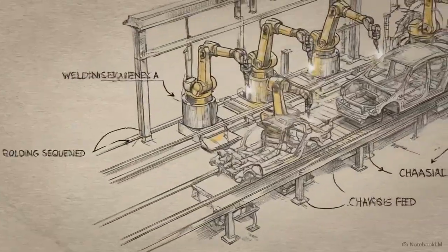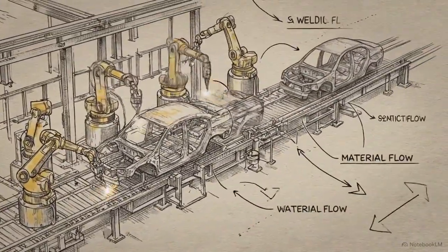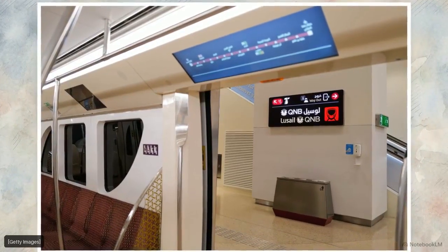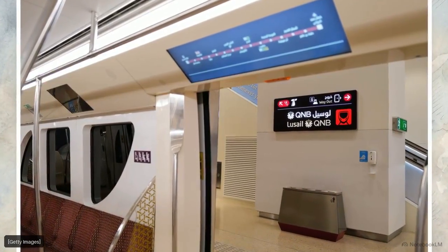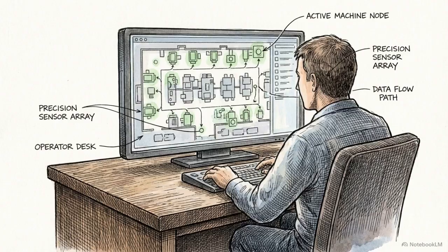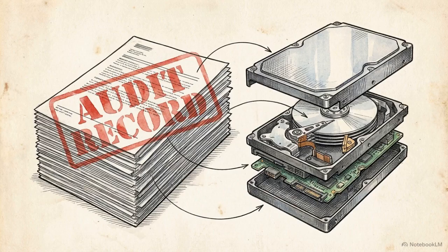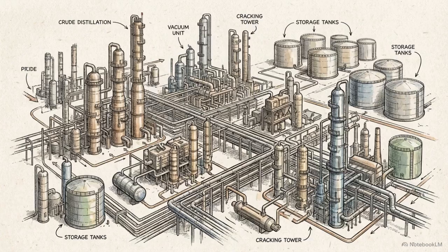While a local PLC controls a single machine, a BACS coordinates the complex sequences and overlapping dependencies of disparate machines across entire plant areas. The Doha Metro provides a prime example. Its building automation system integrated redundant hardware with SIL-capable fire life safety functions, accelerating the commissioning time for the entire public transit network. At this tier, SCADA systems manage operator situational awareness. They translate raw data into human-machine interfaces, managing complex alarm hierarchies so operators can monitor the plant safely. The historical telemetry archived by these supervisory layers serves as the definitive record, used to shorten troubleshooting cycles and conduct rigorous safety audits. The supervisory layer transforms isolated machine logic into a coordinated, auditable operation across the entire plant, while maintaining the safety integrity of the underlying hardware.